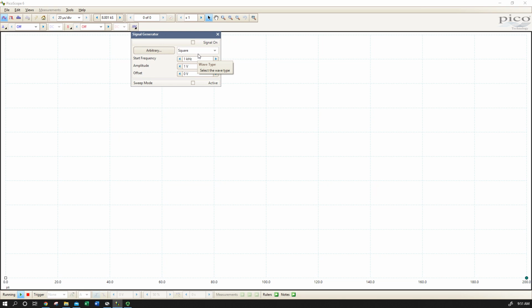So what that means is when we're looking at especially the Q factor of a resonant circuit, we need to remember that we've already got a 600 ohm resistor in series with whatever circuit we build. So we've already got a good bit of pure resistance in this circuit. So if we look at how steep our resonance peak is, it's always going to be limited by that